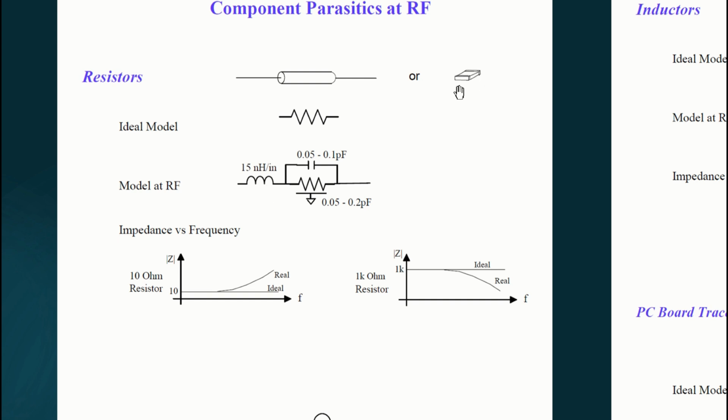Now, in the upper right here is a surface mount component, and you might think that, well, it doesn't have leads, so it doesn't have any inductance, but that's not true because, well, when current flows through that, it also creates a magnetic field around it, but there are traces on the board that extend out from these locations. So we always have to worry about parasitic inductance and compare its impedance to the resistor value, for example.